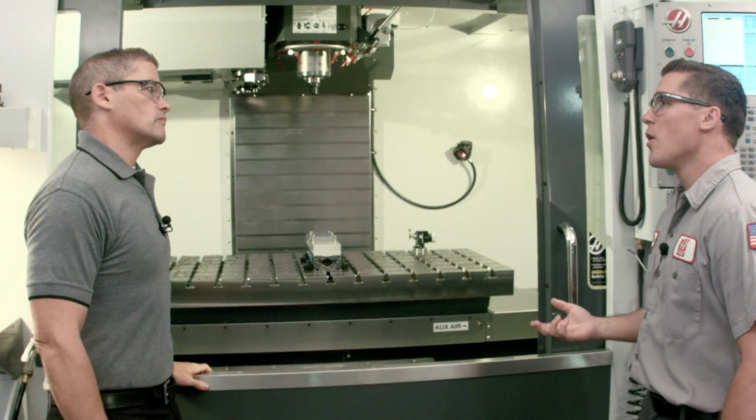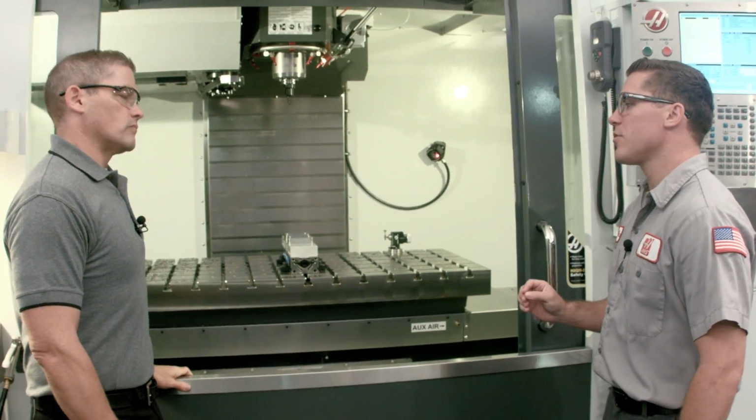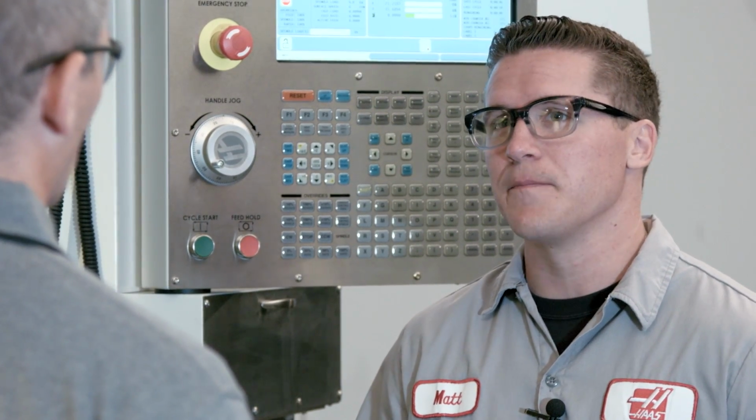So, Matt, why is anyone going to go to the trouble of implementing another tool lubrication system when their flood coolant is working just fine? When a shop needs to machine parts where water-based coolant just cannot be used, this sets them on a path to finding other ways of keeping their cutting tools sharp. Using MQL, you consume at a minimum 5 times less the amount of concentrate than you would when using flood coolant. And depending on your material and cutting tools, there's potential to improve tool life as well.